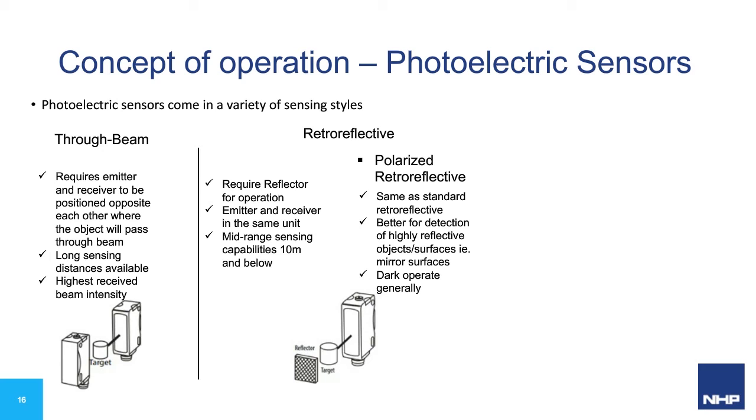Now it's important to note that the shorter range comes as the light travels twice the distance when leaving and coming back from the sensor. And it's also important to note that the light beams actually spread outwards in all directions from the light source, and so there's less light concentration at a specific point the further out you go from the sensor. So laser sensors do help with this, however. Now, moving on to the next one, diffuse sensors.